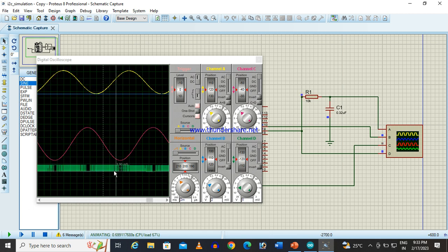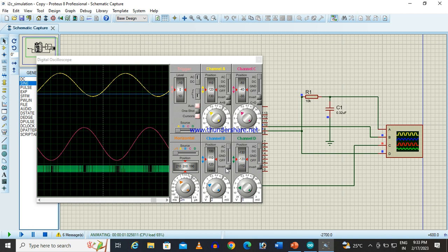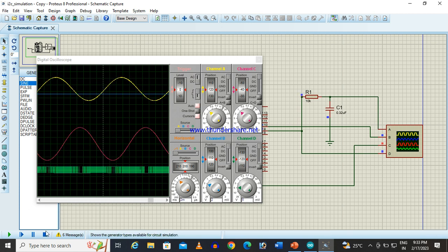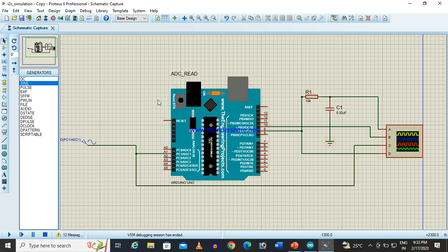You see, this green color is the PWM pulse which will be going to the inverter. Here there will be a module. We have to make a board that, in the case of a 3-phase inverter, receives the modulating signal from the PLC after processing. Then the complementary PWM pulses for the 3 phases are given to the inverter stack, and it will rotate the motor. This is the idea.